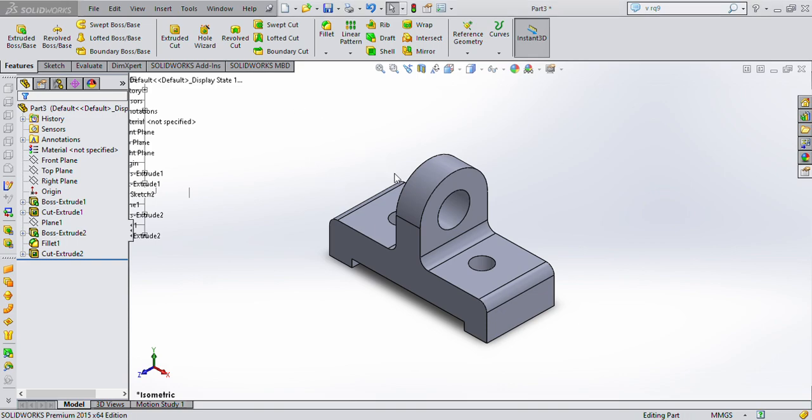Okay, let's say this PC, this is my part 3 in my case. You may put a name for your part, okay? Now, be careful: if you do not save your part, it is not possible to continue. That's why you should definitely save your part, okay? I saved the part. Now I can go to File, Make Drawing from Part, okay?